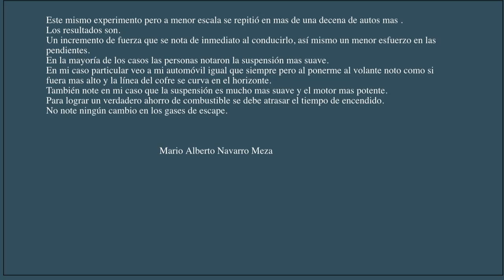richer in gasoline. So you have to put an extension, which are for sale in auto parts shops, on the sensor in order to get a reading of less oxygen, which will be translated as it needs less gasoline.